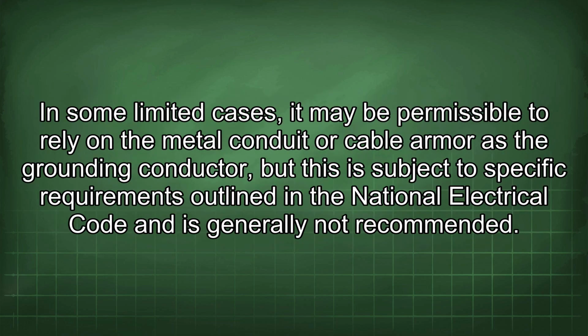In some limited cases, it may be permissible to rely on the metal conduit or cable armor as a grounding conductor, but this is subject to specific requirements outlined in the National Electrical Code and is generally not recommended.